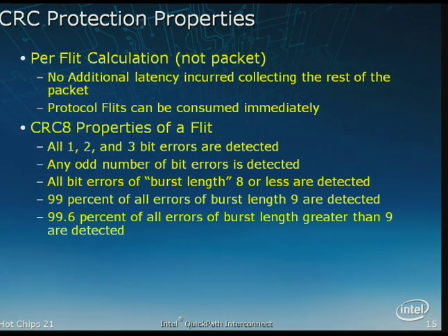The general properties of CRC8 over just 80 bits: it protects you on 1, 2, 3-bit errors, all odd number errors, 99% of all burst length of 8, 9 errors, and 99.6% with burst length greater than 9.